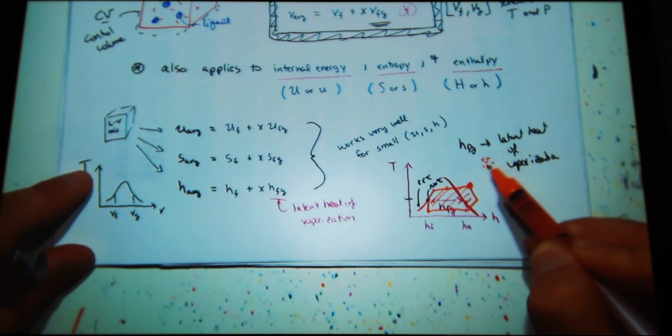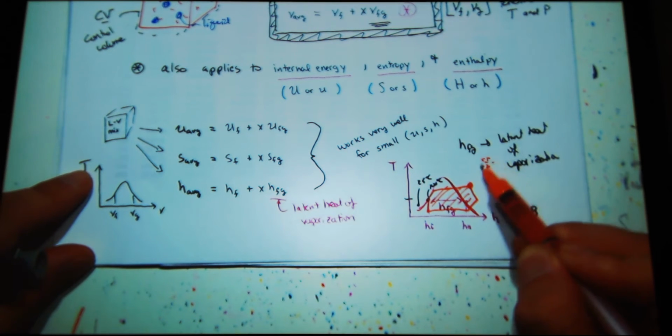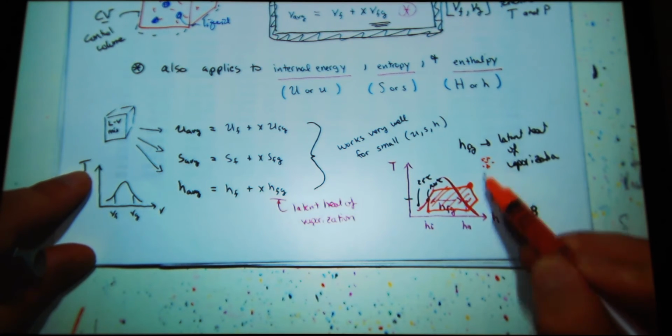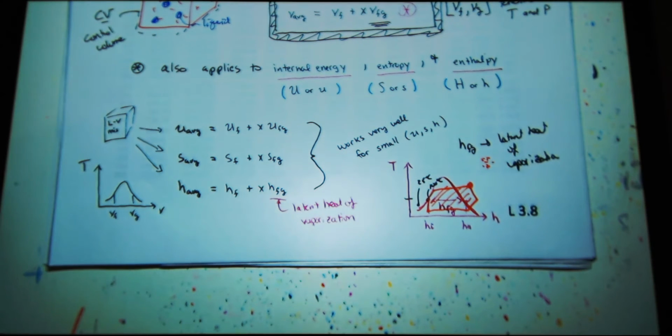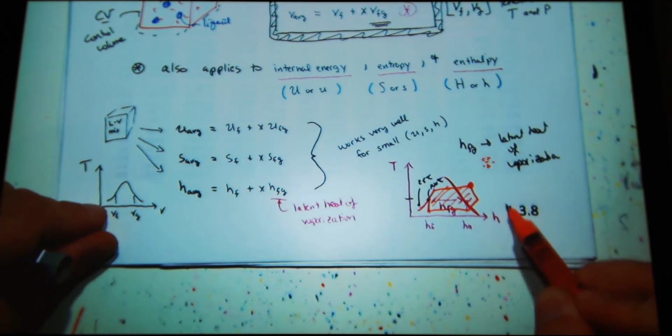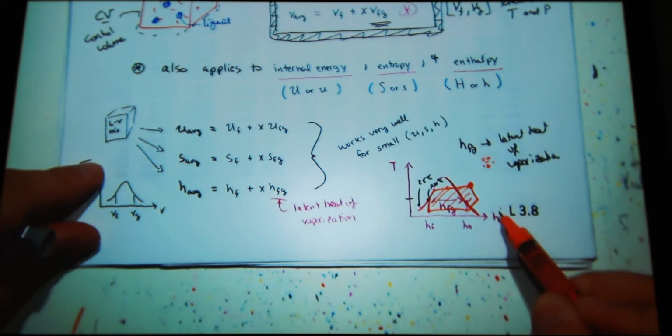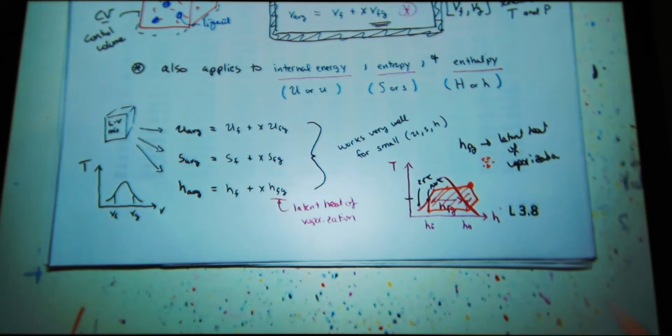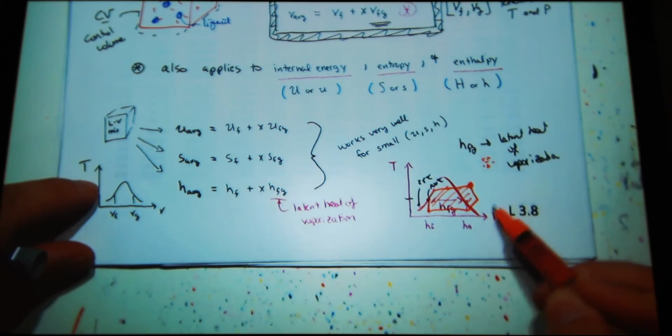If we're supposed to be here but we're way out here, that means we're heating it up way too much. We have more superheated vapor than we should expect, so maybe we have an insulation problem. If we're getting points down here, it might be a little different. That would suggest maybe we have a leak, probably more of a leak.